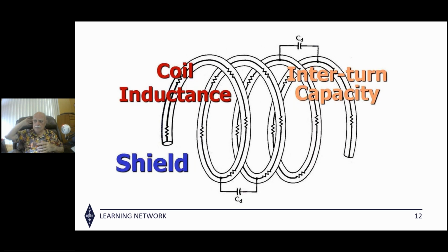Where does the current go on the outside of the coax? I'm not Merlin, so I can't answer the question. Where does the current go in an antenna? Well, it flows down the outside of the coax. It depends on how long that coax is, what's at the other end of the coax, what kind of ground it passes over. It's a very difficult question to answer. But in any respect, because that outside shield is a partly tuned element, it's going to be part of the antenna. So your antenna isn't just 2 wires up there making a nice clean radiation pattern. Your antenna is a 3-wire dipole with a 3rd wire that's making all sorts of ugly radiation in the wrong direction. So there's no pat answer to where does it go. It makes RF.